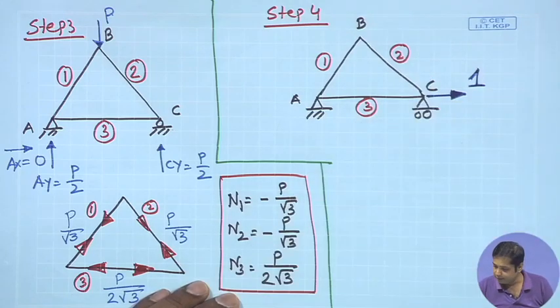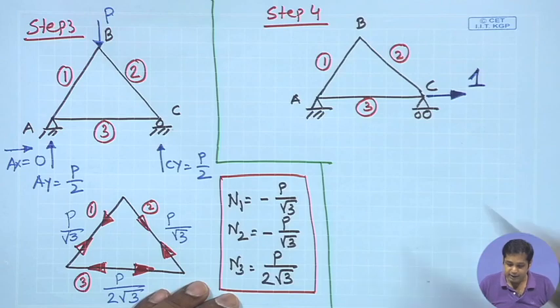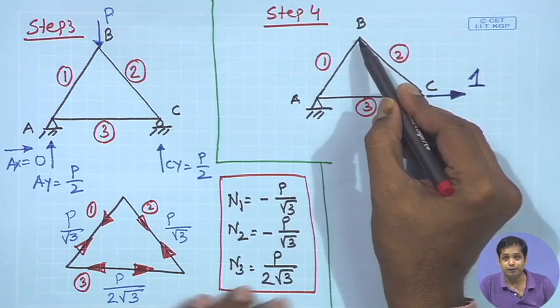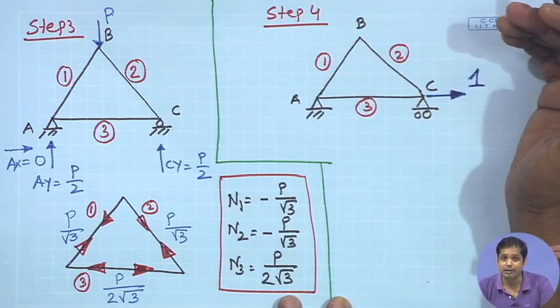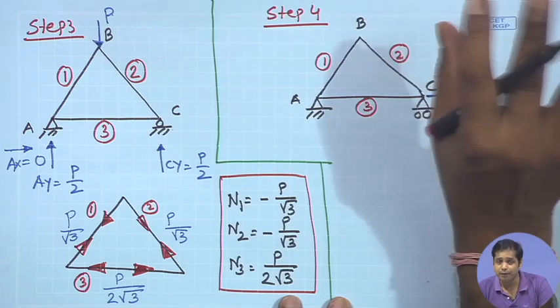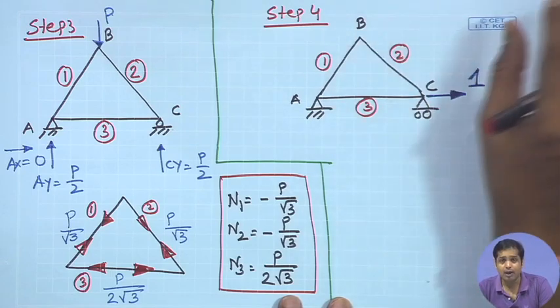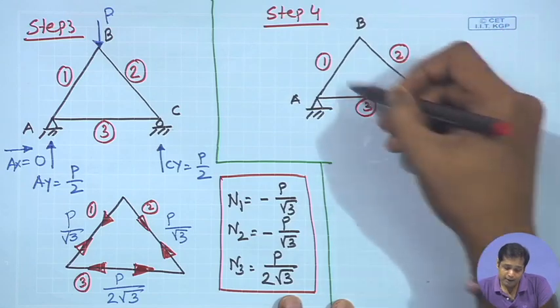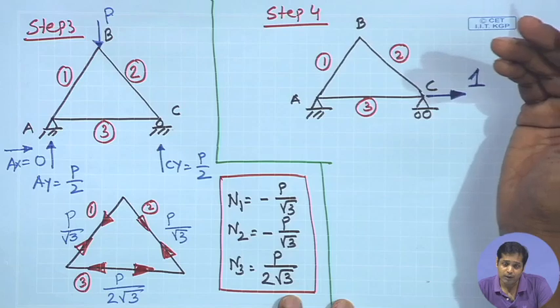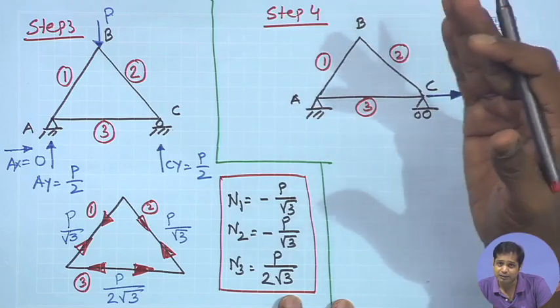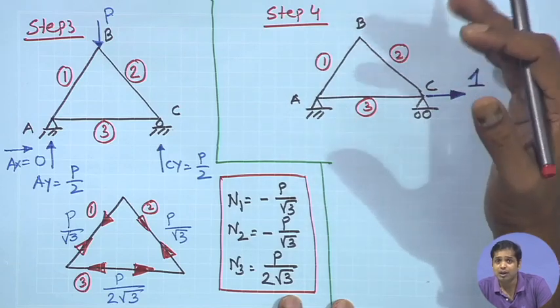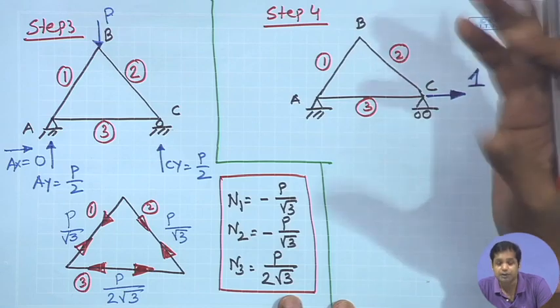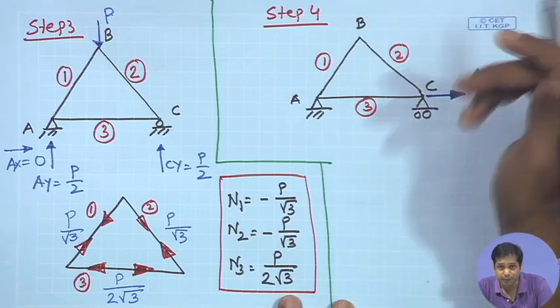So, let us analyze it, and if we analyze it, then you see, by just looking at this structure, we can say, consider this joint. If you remember, when we analyze a truss, first thing we see if we have some information about the truss or not, which can reduce our computation. In this case, one way is to identify if there are members which have zero force, okay, zero force members.